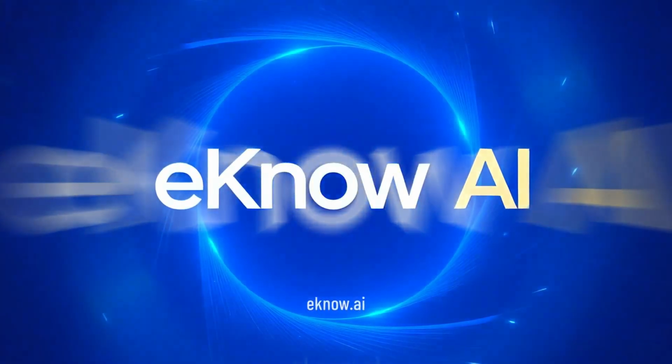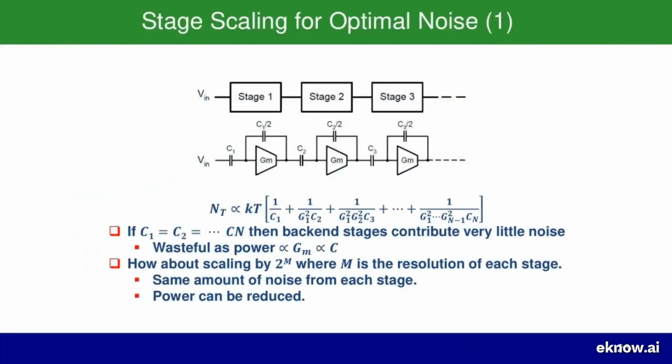Following up on the noise distribution we just discussed, let's take a closer look at this formula for the total input referred thermal noise, NT. This equation really dictates our design strategy. First, let's consider a straightforward approach. What if we just make all the sampling capacitors the same size? So, C1 equals C2, C3, and so on all the way to Cn.